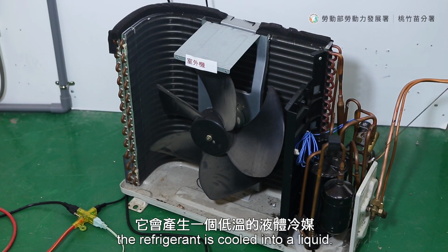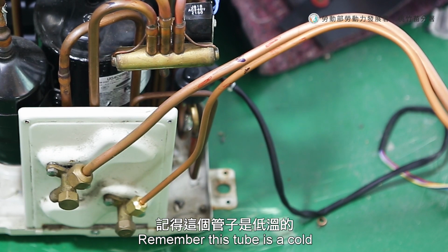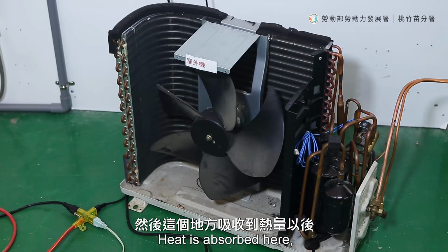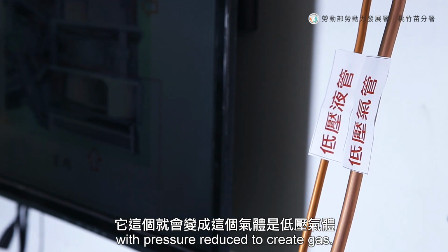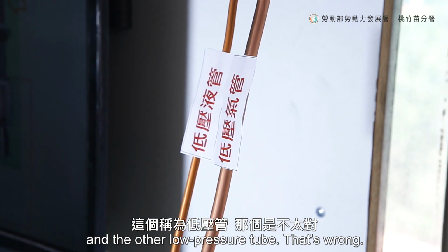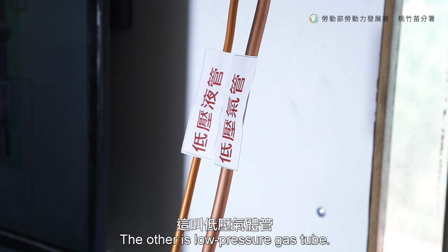And here, the refrigerant is cooled into liquid. Remember, this tube is called the low-pressure liquid tube, which leads to the evaporator. Heat is absorbed here, with pressure reduced to create gas. Some AC technicians call this the high-pressure tube, and the other the low-pressure tube. That's wrong. This is called the low-pressure liquid tube. This other is the low-pressure gas tube. They are both low-pressure tubes.